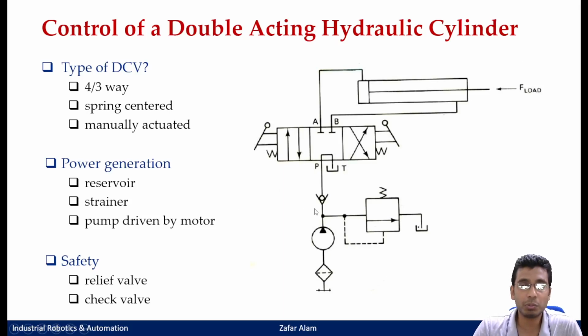In this case, what would be the direction? From bottom to the top. That is connecting your pump outlet to your valve inlet. That means your flow can only be like this, through this way, and your flow cannot be the opposite side. Okay, it cannot be from your valve. This is your DCV, na, from DCV to your pump.